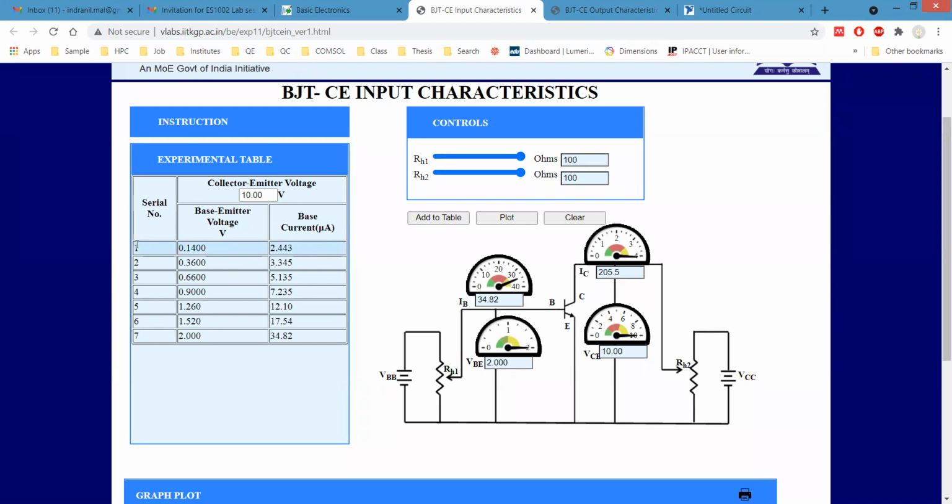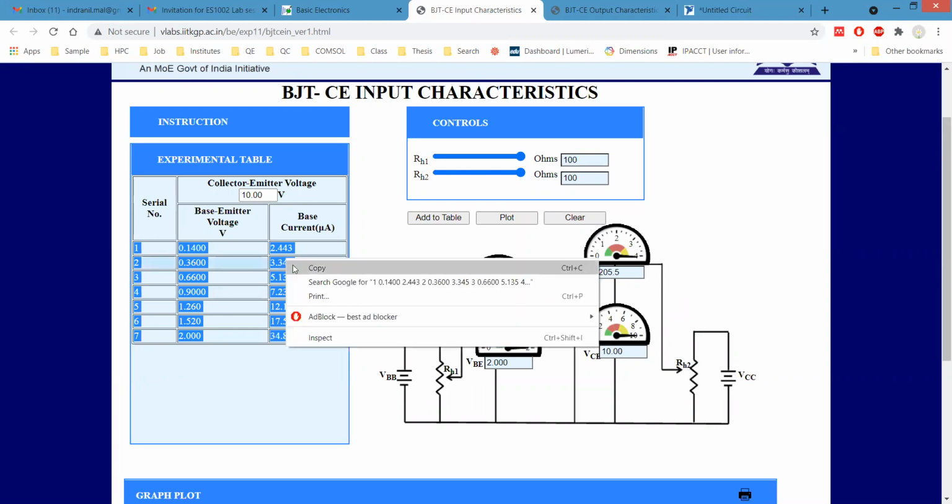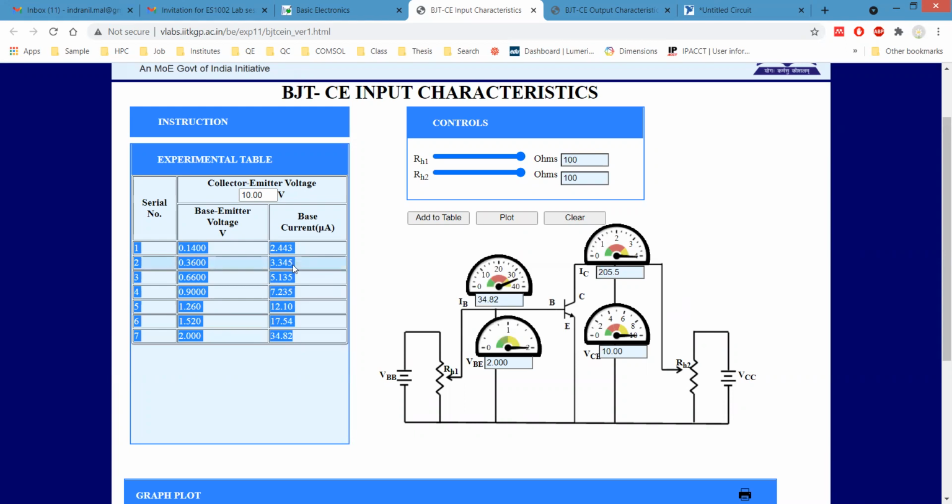Yeah, now you are absolutely correct, because our base is P type. You can see the positive side is connected to the base directly or through the resistor, so that is why it is in forward bias. And the collector is N type because it is an NPN transistor, but from here you can see it is also connected to the positive side. So N connected to the positive side means it is in reverse bias. So both of you are correct. Thank you for at least telling this.